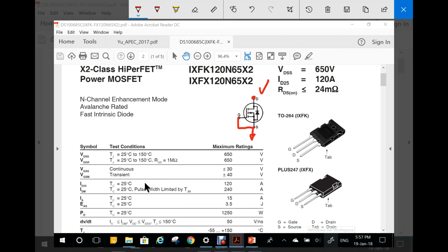And then it also says that if you put, this will be the second line here, 1 megohm, here it is, between gate and source, and then impose this voltage, 650 volts, it will also be okay. Now this is important because in some cases drivers might have high impedance, so high resistance at the output. Well, not 1 megohm, but it could be high. And suddenly it might have some leakage so that the impedance is high.